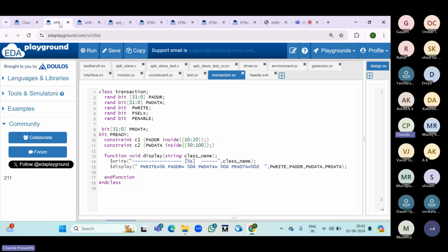Okay. So in Verilog HDL, we use both procedural and continuous assignment. There we have reg and wire data types. So there will be confusion about when to use reg and when to use wire. Sometimes there will be mismatch errors, because we use inout signals also, right?